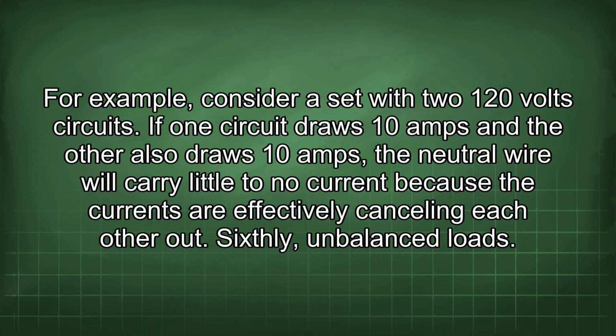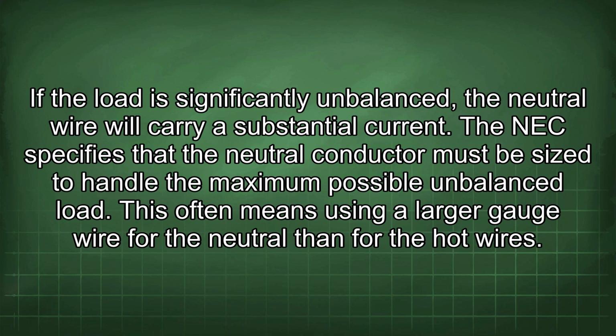Sixthly, unbalanced loads. If the load is significantly unbalanced, the neutral wire will carry substantial current. The NEC specifies that the neutral conductor must be sized to handle the maximum possible unbalanced load. This often means using a larger gauge wire for the neutral than for the hot wires.